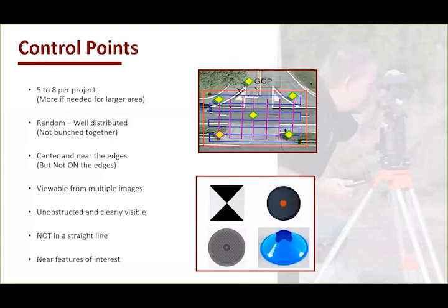Most photogrammetry software will ask you to place about 5 to 8, but not to over-inundate with control points, potentially overloading the algorithms working through a solution. They're randomly placed out into maybe the four corners, but not to the far extreme of the corners, and maybe something in the center. And then with some type of laser measuring device, either an LTI system or electronic total station, or if you have a GPS, you are physically measuring those points.